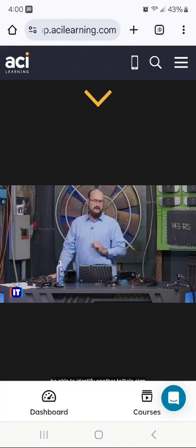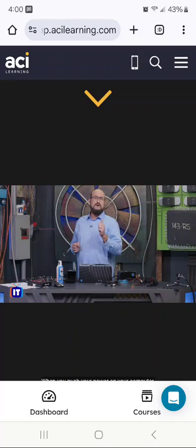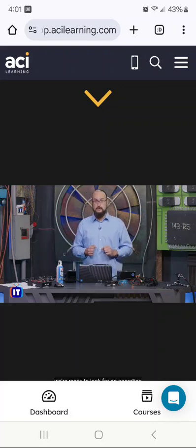Another telltale sign that you have some issue with any of these components, but we'll mention here in the motherboard, is listening for POST beeps. When you push the power on your computer, you should hear one beep. That is a POST beep letting you know that the power-on self-test found all of the hardware that was connected to the motherboard, and we're ready to go, and we're ready to look for an operating system to bootstrap the hardware.